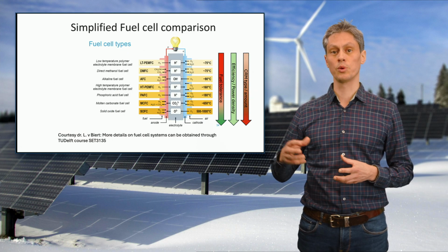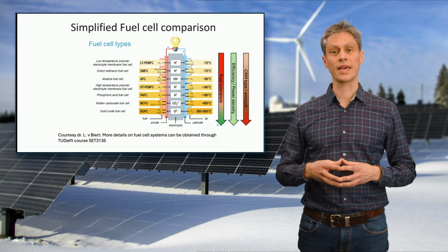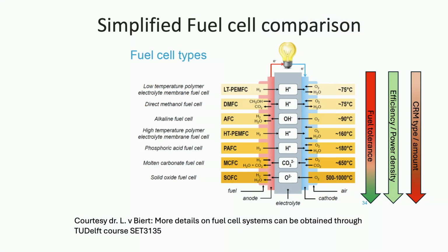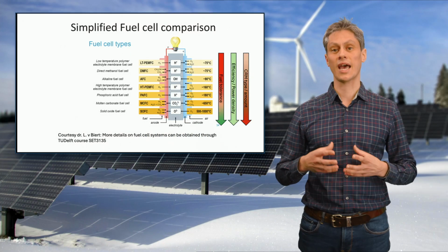Of the many types of fuel cells, the solid oxide fuel cell can combine thermochemical gasification and reforming reactions with electrochemistry and is therefore considered the most compatible with most directly gaseous carbon-rich biofuels. Overall, it uses less quantity but more diverse and specific types of CRMs like nickel, yttrium, scandium, zirconia, and lanthanum, and even gold and platina to catalyze the thermochemical process and transport charge simultaneously at the higher temperature.